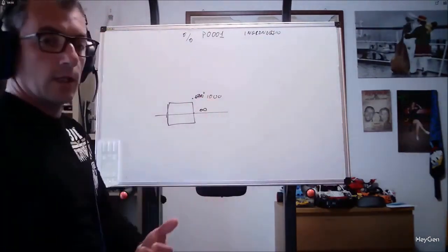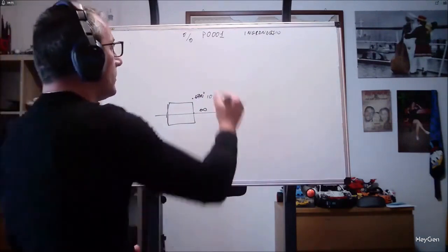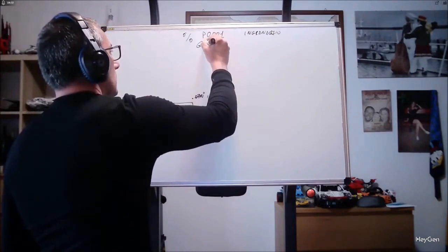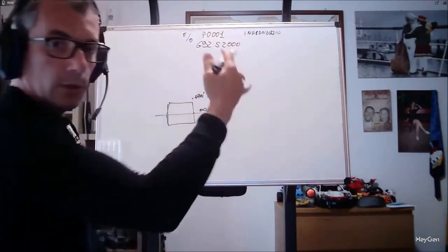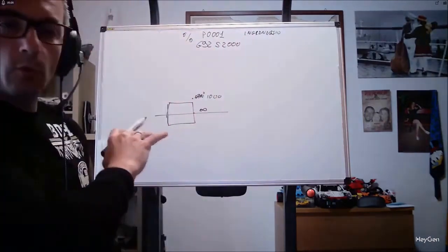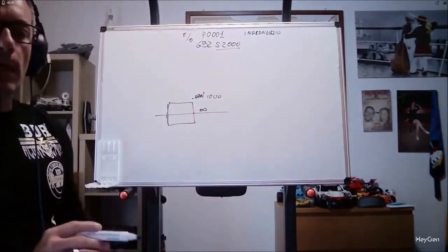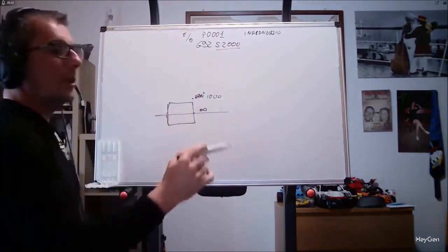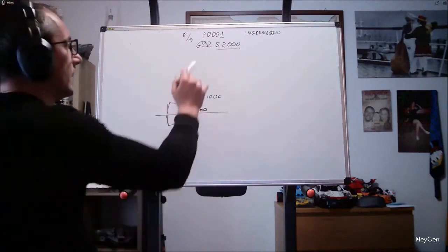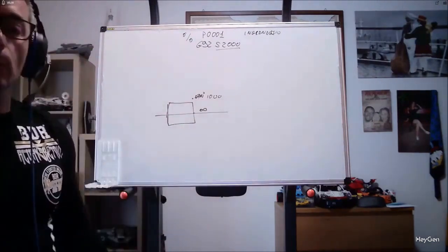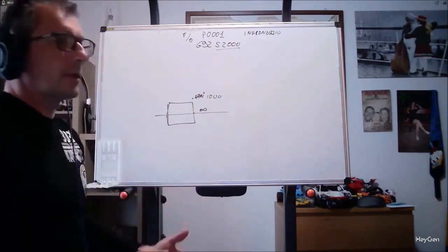So normally, depending on the type of machine and the weight of the piece, and some variables related to the grip, if it is a G92, S2000, 3000, 4000, 5000, that is, we tell the machine that at any moment during processing, you can never exceed these RPM numbers. G92 is repeatable within the program, meaning if we perform multiple operations and want to change the maximum RPM for safety reasons, we can do so. So if we have a piece weighing 80 kilos, we can do it.